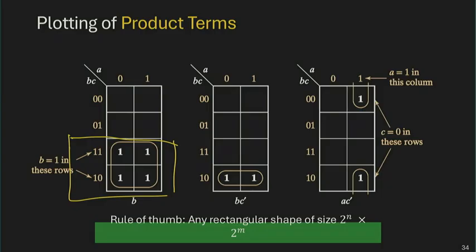And finally, the wraparound one is a little bit harder to identify. Just always pay attention to it. Maybe put down one sentence on your cheat sheet saying to pay attention to wraparound implicants or product terms. For that top and bottom, they share the same condition of A equals 1. They happen on that side of the Karnaugh map. And then what do these 2 rows have in common?